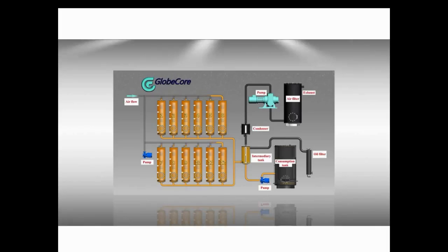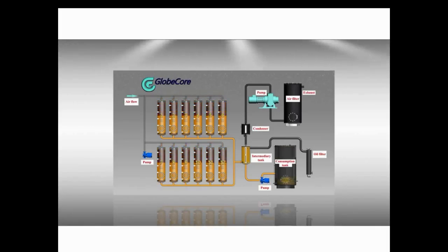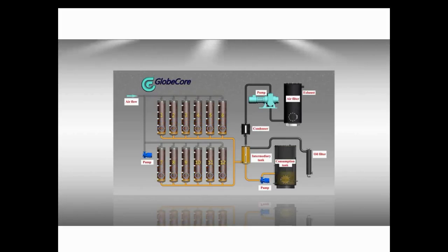In this design, Fuller's earth reactivation is fully automatic and enables a regeneration plant to process oil again and again using the same Fuller's earth. Once poured into the column, Fuller's earth doesn't need to be removed from the plant for 2–3 years. The concept has changed.